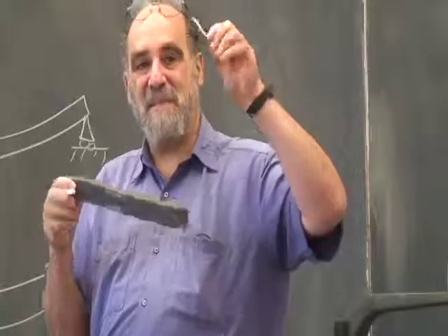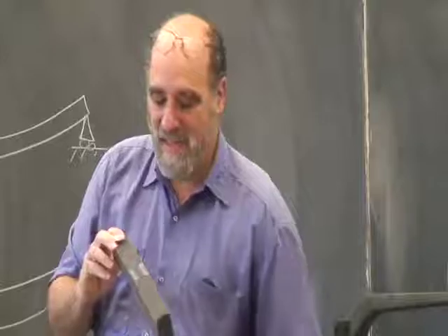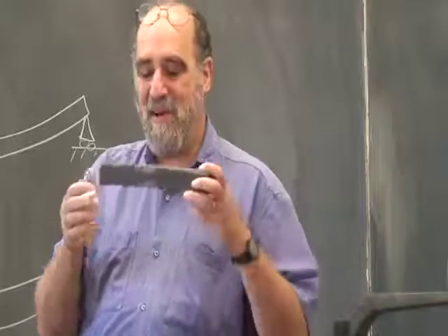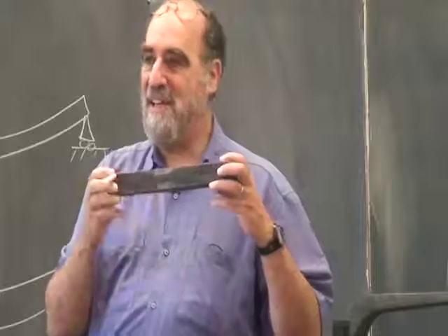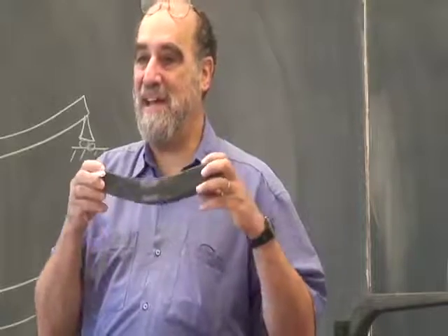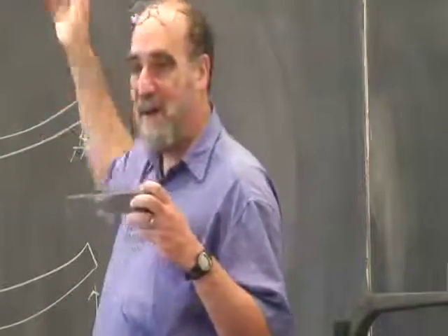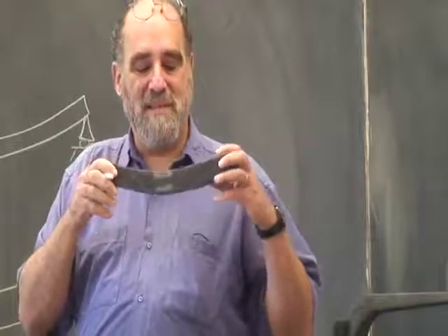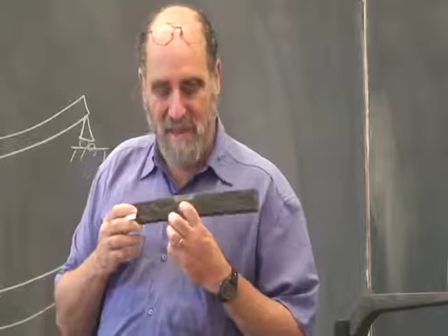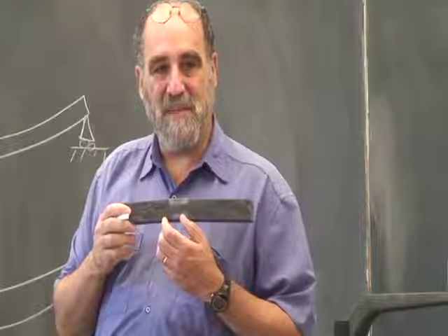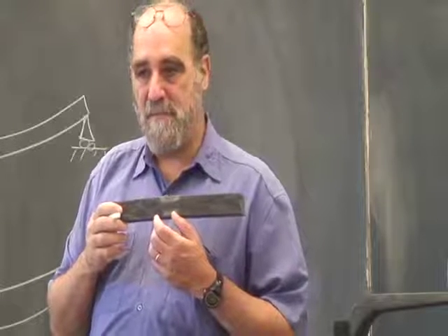And each of those fibers is in a tension experiment. So when I bend this, there are all these fibers here that are compressing and here that are in tension. And each of those is obeying this rule that we got for tension, which is that this is getting shorter and this is getting longer in accordance to the fatness of the fiber and the length of the fiber by the formula we showed there.